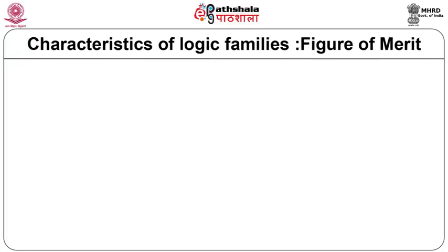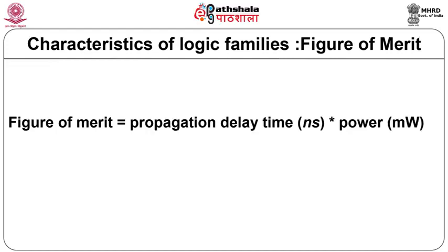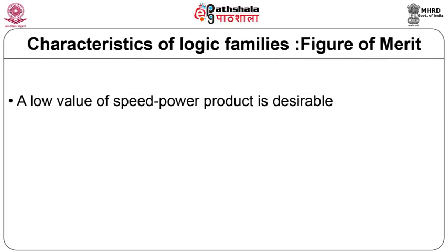This is the most important parameter, that is figure of merit. Figure of merit is equal to the propagation delay time expressed in nanoseconds multiplied by the power in milliwatts. A low value of speed power product is always desirable.